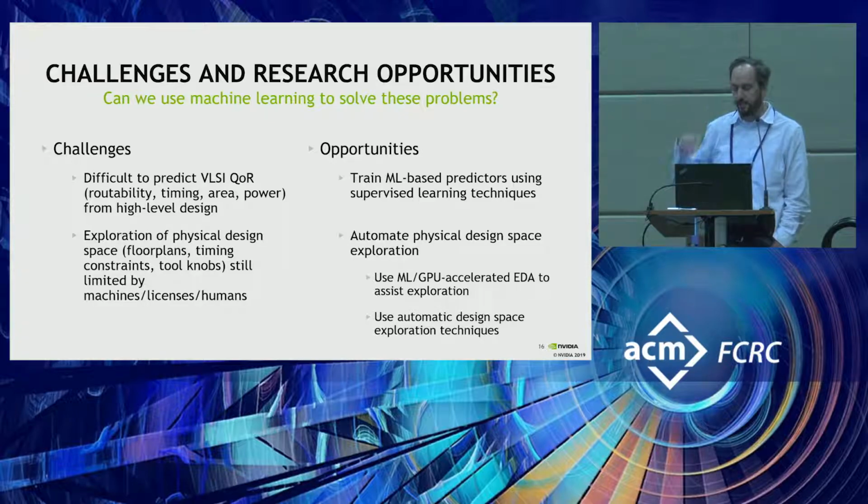The question is, would you use this to build a full chip using, say, SystemC as we demonstrated? There are still some challenges. Design verification was mentioned as one. Although the vendors are working on it, there's still not a C++ to RTL formal equivalence of what we have with RTL to gates. The second issue is maybe even trickier: even if you did have that formal C++ to RTL equivalence, I can't necessarily do all of my verification at the C++ level and not repeat the verification at the RTL level.